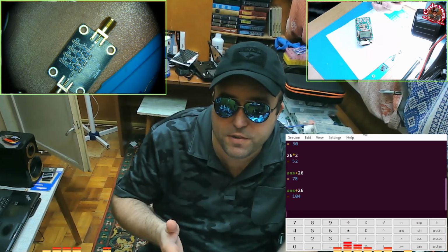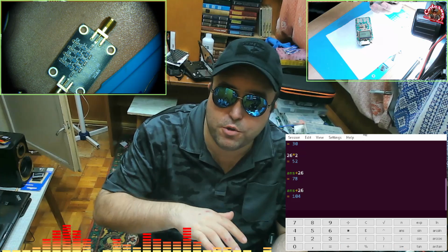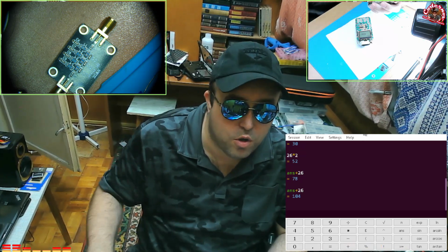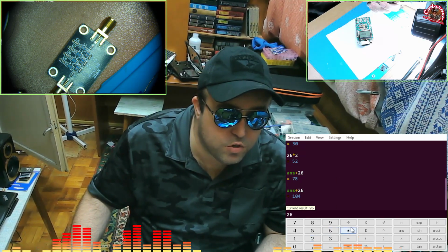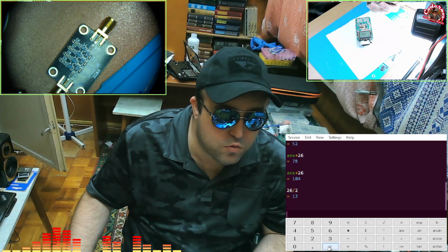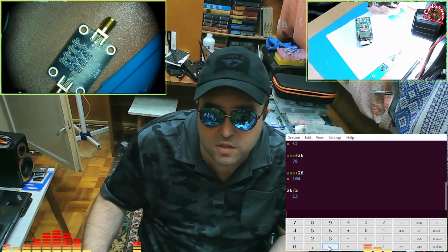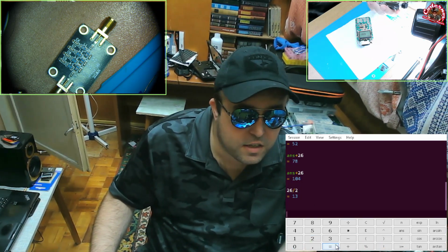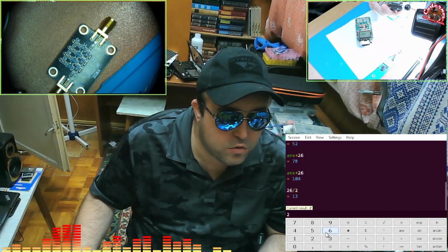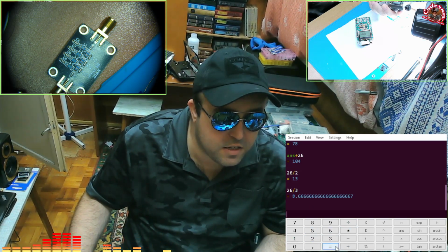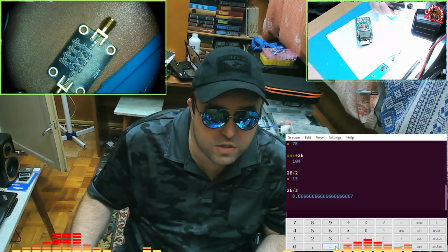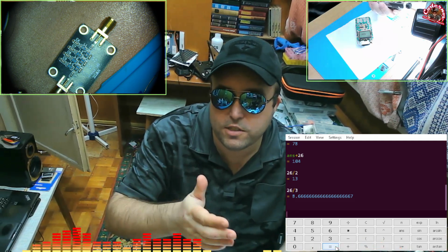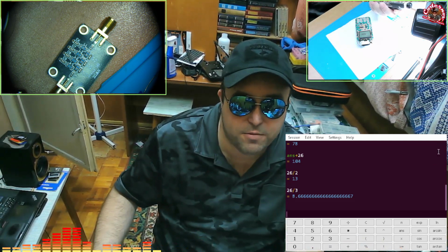You cannot receive anything on those frequencies because the radio receives internal clock. Also, we can do 26 divided by 2, which is 13.0 megahertz, or 26 divided by 3, 8.66, etc, etc. All those frequencies are dead frequencies.